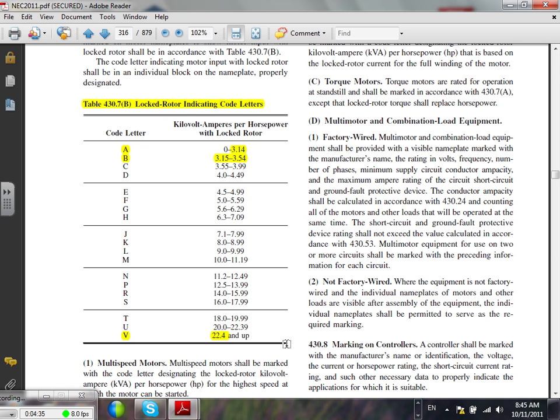If you grab that conversion mechanism, which is the rotor, grab it, I hope not with your hand, grab it with some means and lock it and turn the switch on, all this energy coming to the motor is trying to be converted to mechanical energy, fan, compressor, whatever, but it can't do it. So what happens is it starts heating up and heating up and heating up, and at one time it's going to burn your motor.